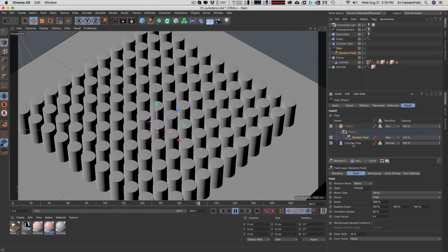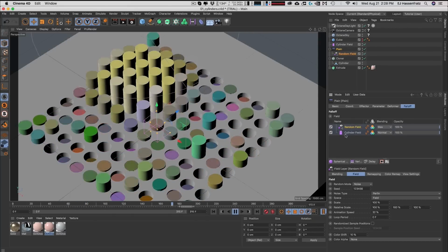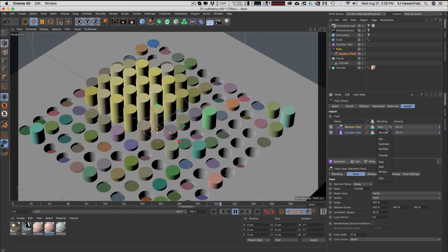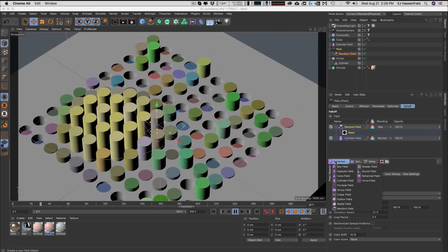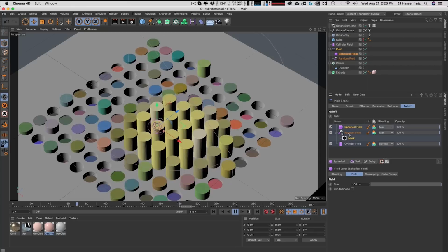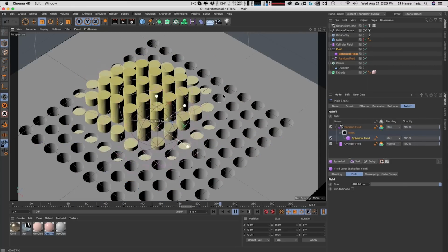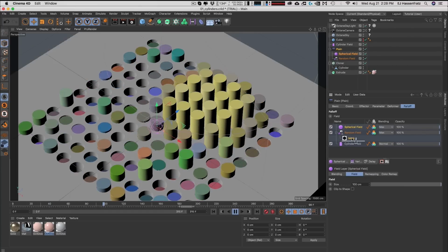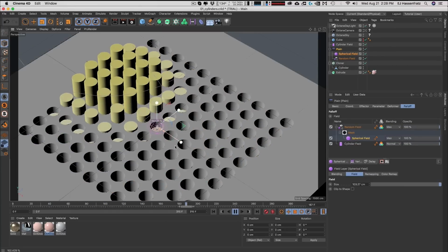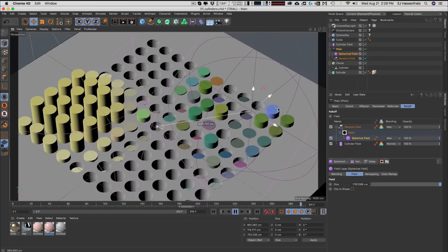Another fun addition to the field layer system is the ability to use field masks. Typically before, you were just limited to using different blending modes to add or subtract effects or mask them off. In R21, you have the ability to select a field, like a random field, create a mask, and use another field to mask the effect of that parent field, which is really cool.